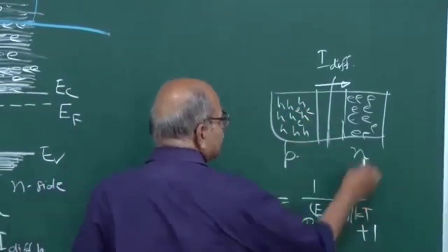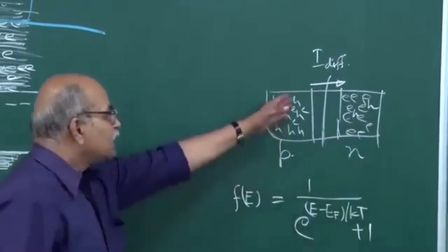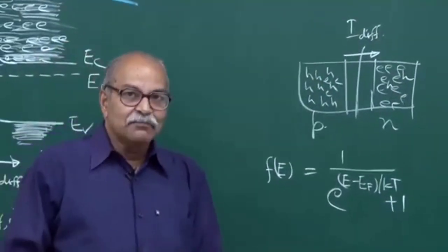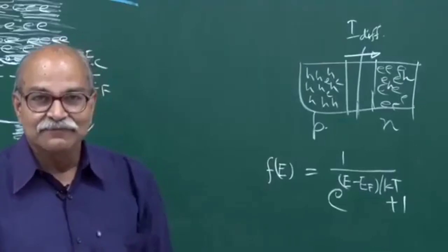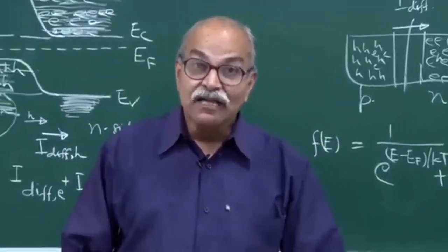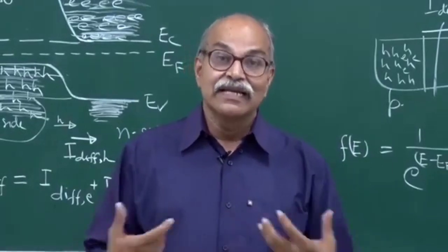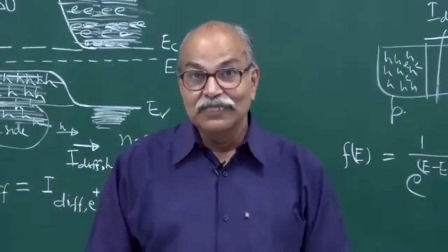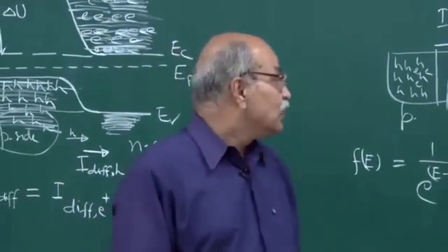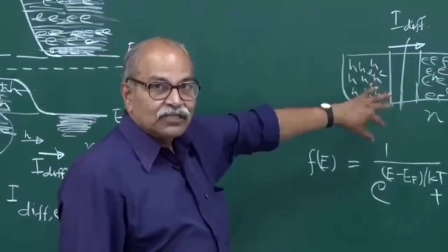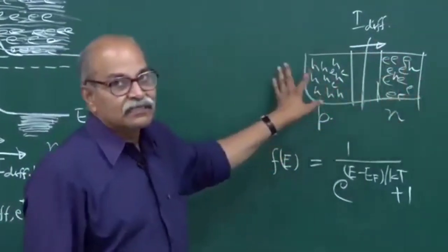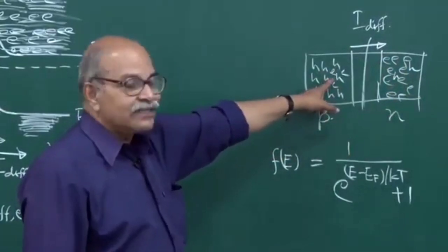If you have electrons here, if you have holes here, from where are they coming? The majority carriers come because we have doped the system with impurities, and minority carriers come because of the thermal energies. Because of the thermal energies, electron-hole pairs are continuously created and continuously destroyed also. Recombination also takes place through some mechanism. So you have recombination and you have thermal generation. Those things keep going in any part of this semiconductor material, and these minority carriers are essentially coming from that.